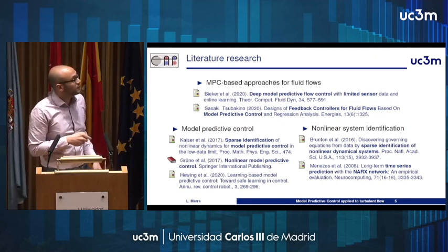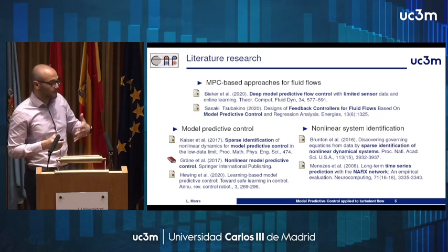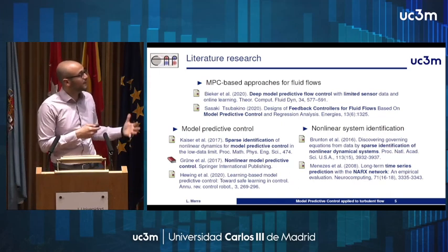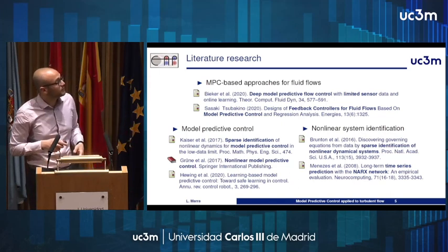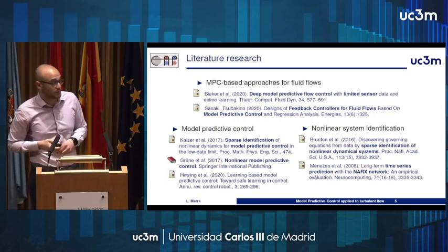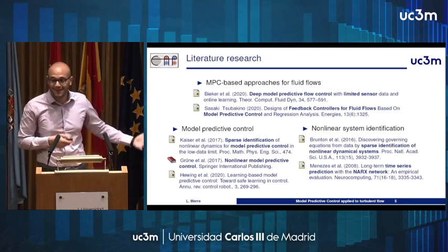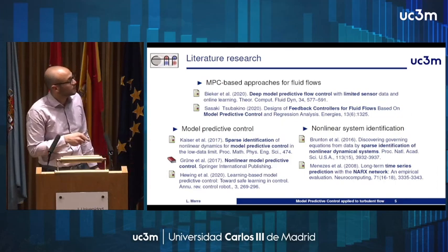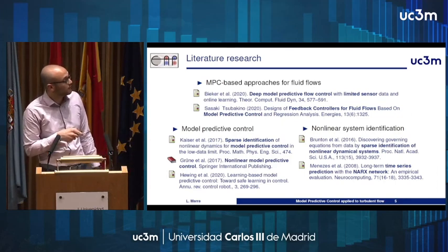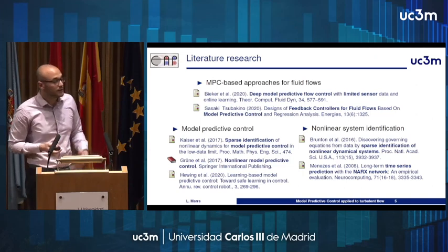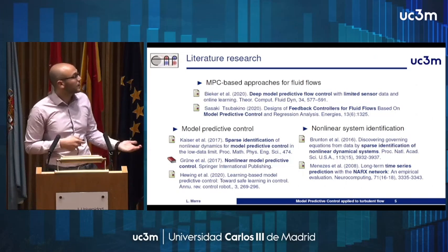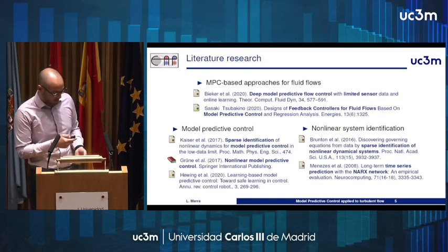And there are different trends in this case. The first one is obtaining an analytical model from data, as the group of Brunton et al. is doing with the sparse identification of nonlinear dynamics. The other one is performing prediction by performing a time series analysis. It's the case of the NARX method, the nonlinear autoregressive exogenous model, in which to perform prediction, we can also include some methods like deep learning.